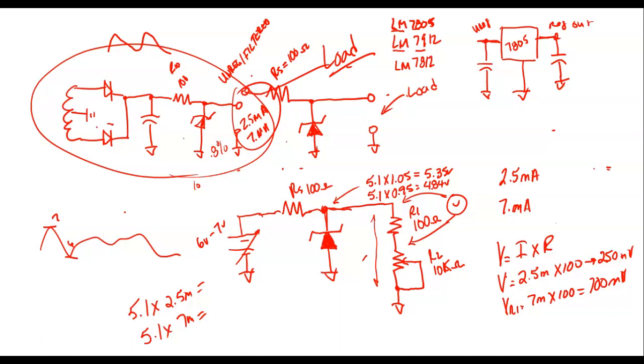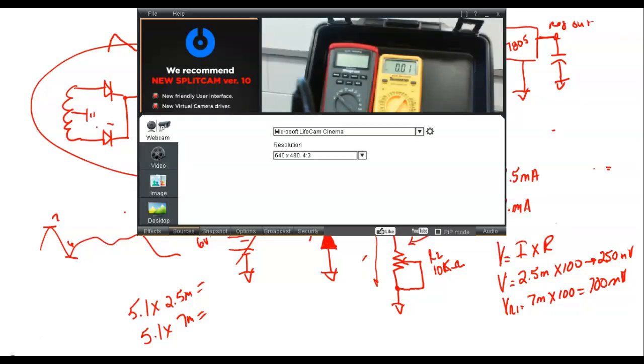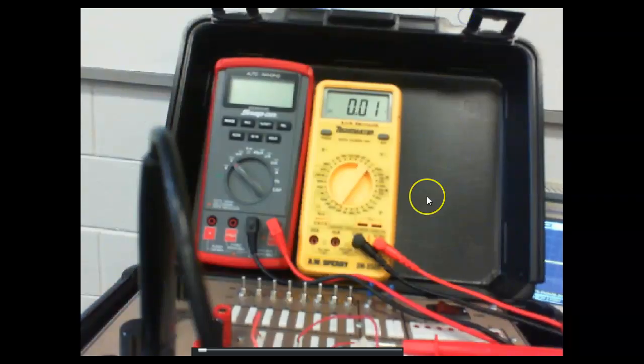I'm so sorry. Okay. And from this one, just to talk it out, we would have to take the V in and get the minimum to 6 volts, and the minimum for the load current would be 250 milliamps. Right. We would bring those down, and then we go to the V out and measure to see what that is. That would give us the answer for that.